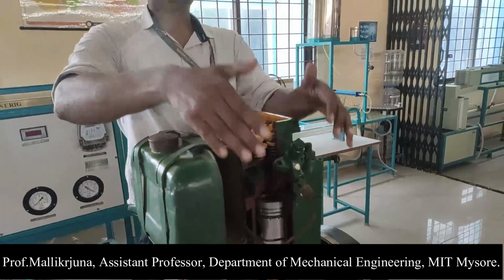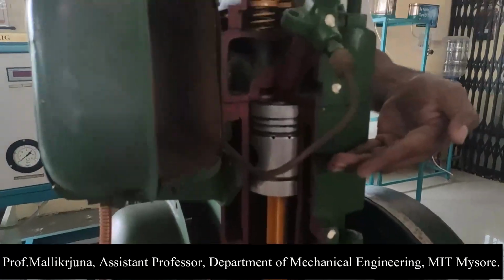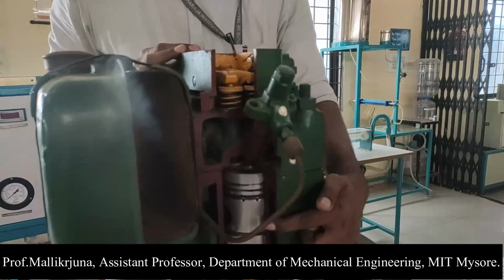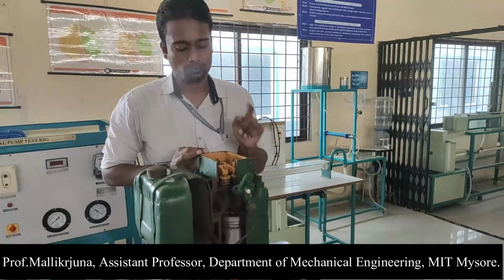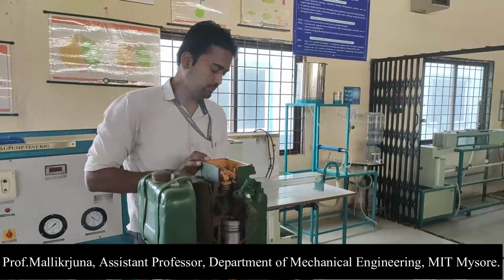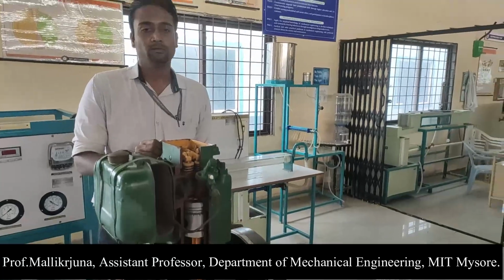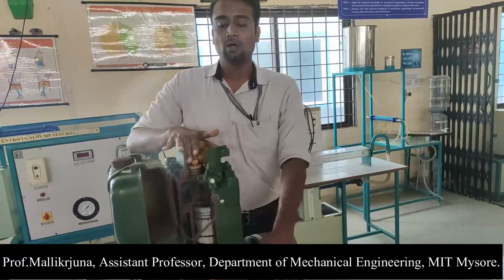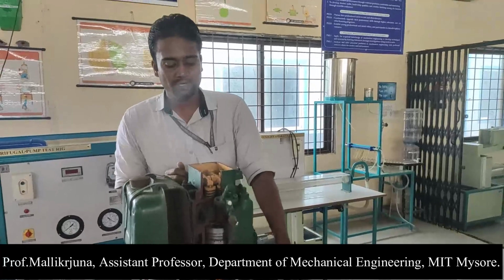Okay, now if you see the piston's position, the piston is exactly at TDC. That means only two options are possible when the piston is at TDC: either I will be at suction stroke or I will be at power stroke. By the adjustment, it is very clear that I am at suction stroke. On this side, the pointer is matching with the TDC position. Now I will give the clockwise rotation to the flywheel so that we can see the valve opening and closing.